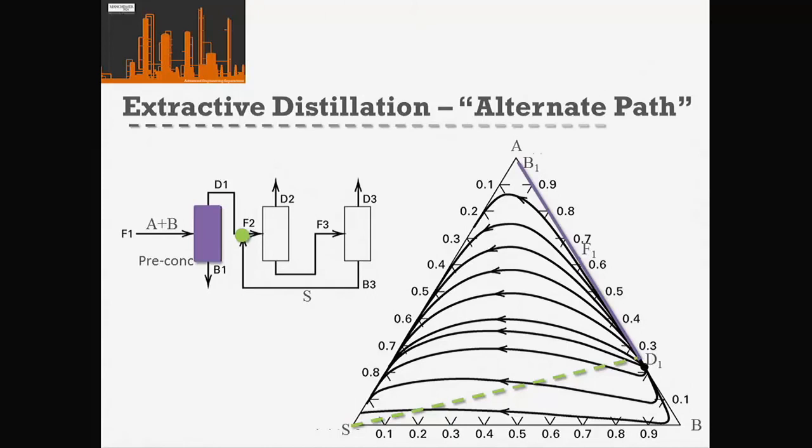And then comes to a bottom product where the two ends of our straight line lie on the same residue curve, okay? So if I start here and come down here, so that's our top product and our feed, I need to lie on this same residue curve that A is on, but there isn't. Yeah, it's impossible to be on the same residue curve because the residue curve just goes around the outside.